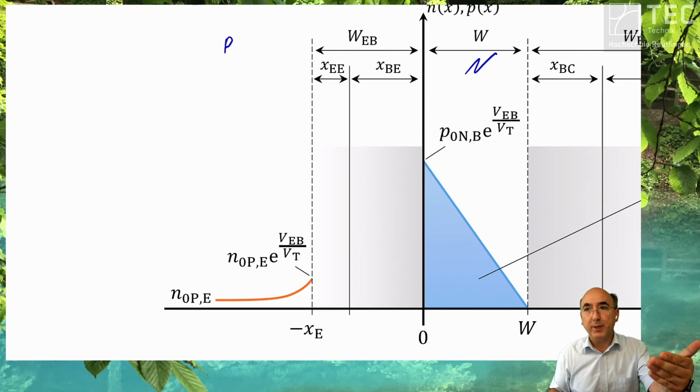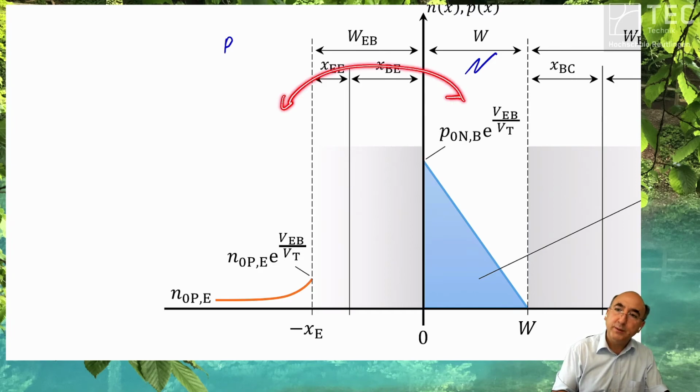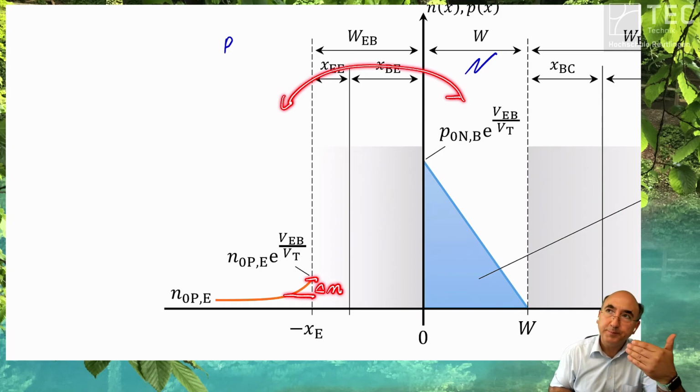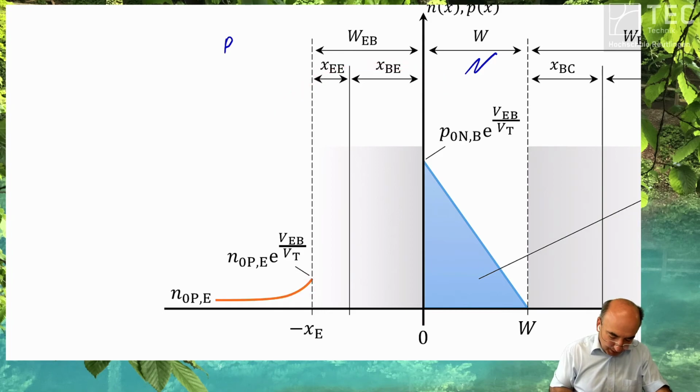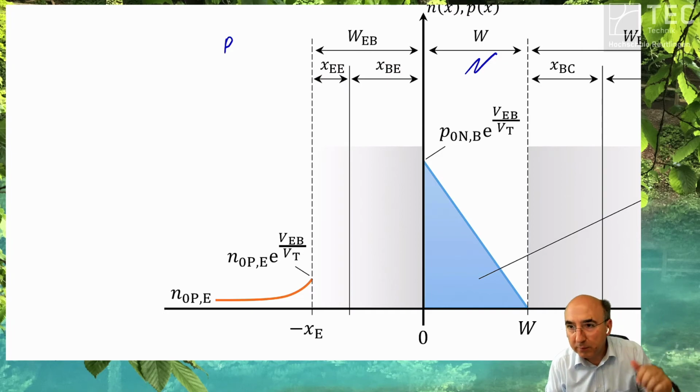Then, in a forward bias condition, you inject the electrons to the P area, you generate your delta N. You remember? So this is your injected additional charge carrier concentration. And this carrier concentration relaxes as a function of the location. We learned that in the range of page 59.